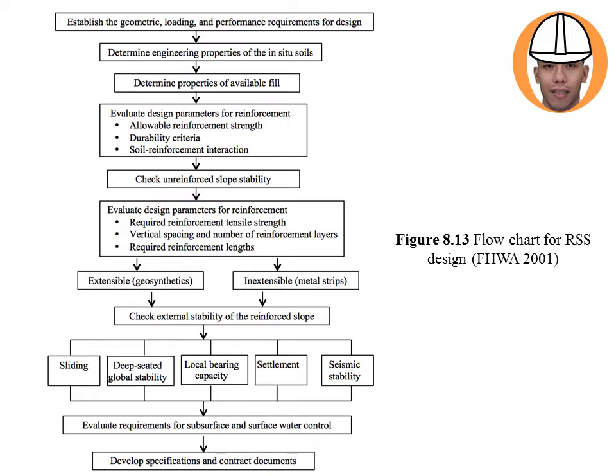So next is the checking of unreinforced soil slope stability, and then evaluate design parameters for reinforcement: the tensile strength, vertical spacing, number of layers, and the length of reinforcement.